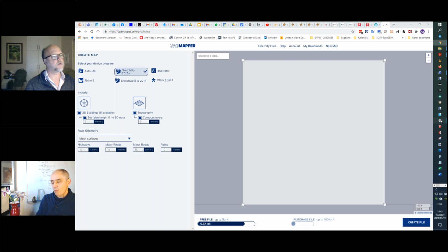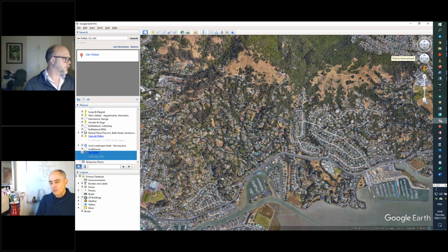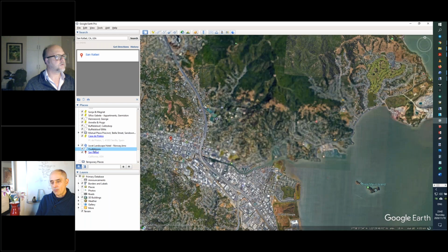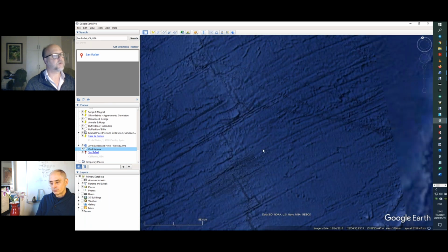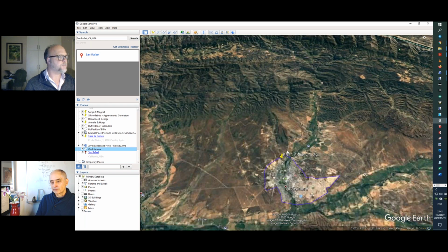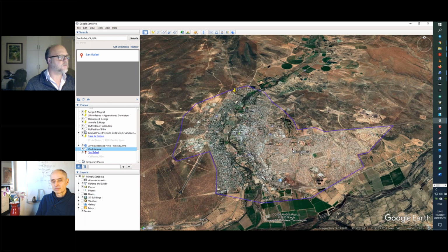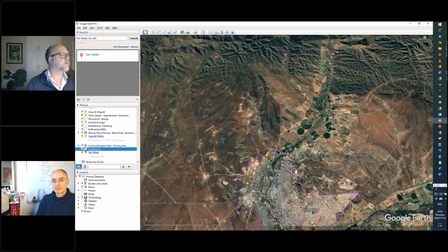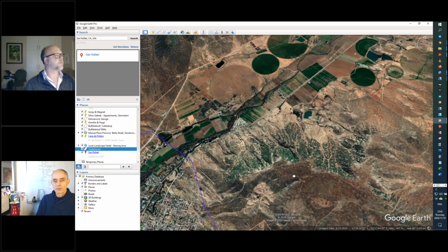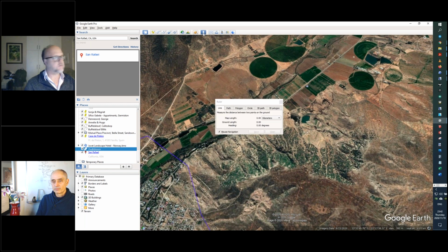Meantime, there you go. So if I go to Oudtshoorn, we could have done it on that end as well. It doesn't matter which area you pick. There's the ruler here, and you can measure a line. In this case, I used a path. You can set your units. You can mark a polygon, and you will get the perimeter as well as the area using the polygon method.